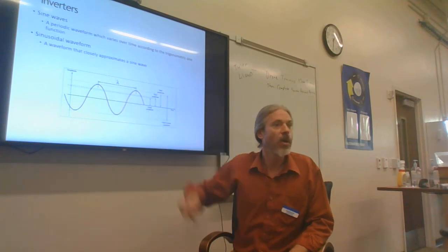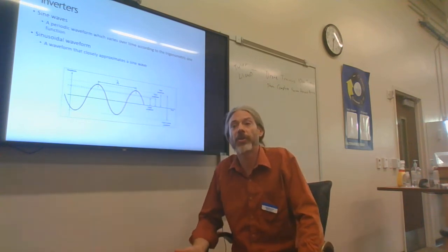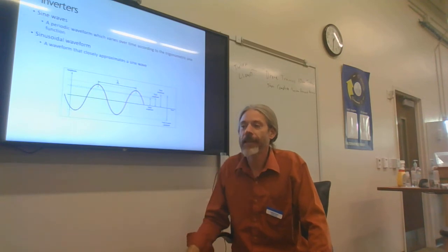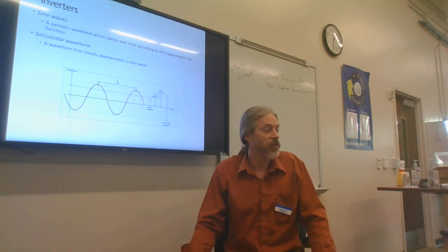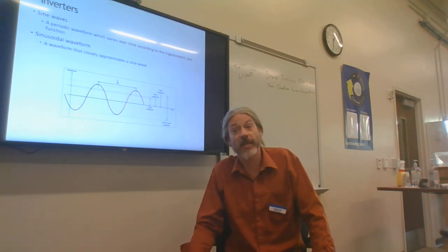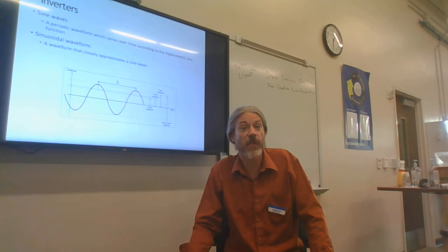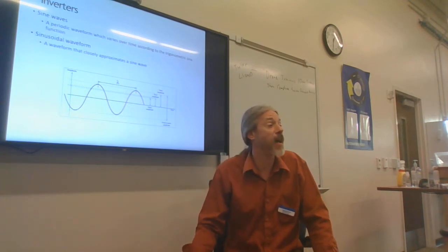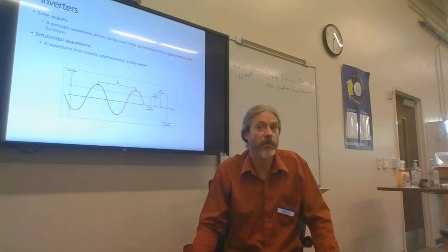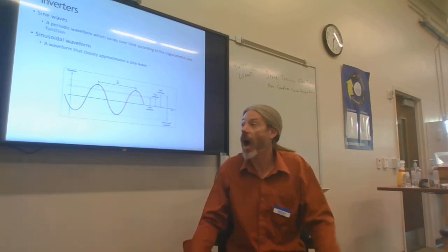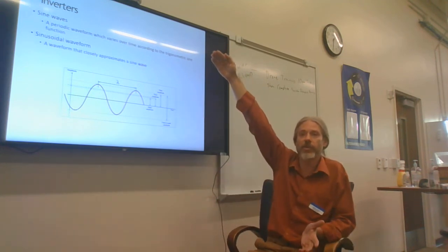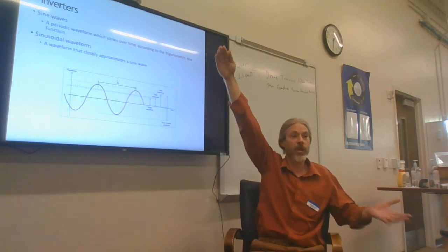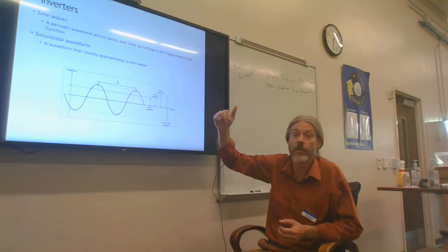All right. So whenever we say the peak voltage is 180 volts, well, the RMS voltage is going to be about 120 volts, which is basically saying that it does the same amount of work as a 120 volt DC power source. A little clearer now? Very much. Awesome. Peak to peak is merely the highest voltage to the lowest voltage, and it is equal to peak times 2.